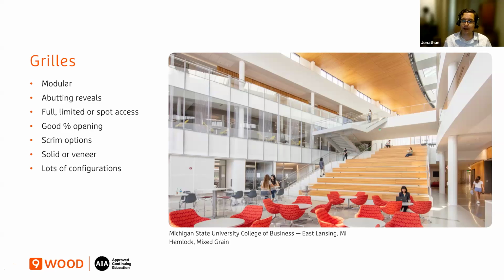The other problem that can happen is if the system is maybe not quite the right one for the installation. A lot of fabrics and scrims can have memory, and so that twist and stuff that happens can read, and it's especially a problem if you have a lot of critical lighting. Like if you have large windows and a lot of critical lighting coming in during the day where a lot is visible, that can definitely be an issue.